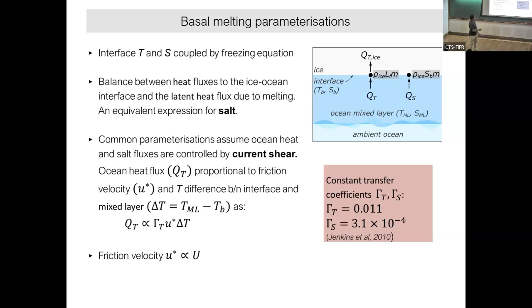Okay. The same is this coefficient here. This is called the transfer coefficient. Okay. And the same thing, we plug in this number and then we get a mismatch. We're saying, oh, there is something different. Of course, these numbers cannot be universal. So these numbers also change very much for different flow conditions. And that's the very important thing to know: which flow regime I am in, which values I should plug in.